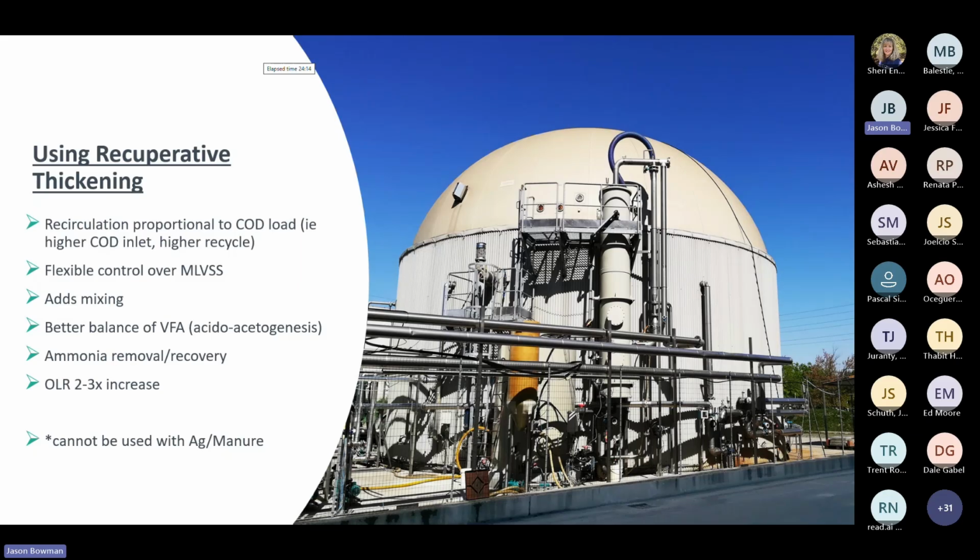Again, going back to the common methods of failure for ammonia toxicity, in these systems, we can actually do what we call ammonia dilution, where we often add in struvite recovery or struvite removal within the side stream of these systems, meaning that we can actually remove or recover ammonia. For those of you that know struvite, it's a 1:1:1 molar equivalent magnesium ammonium phosphate. So we can actually help minimize the ammonia concentration and minimize precipitation in a lot of these reactors by having the side stream struvite recovery process.